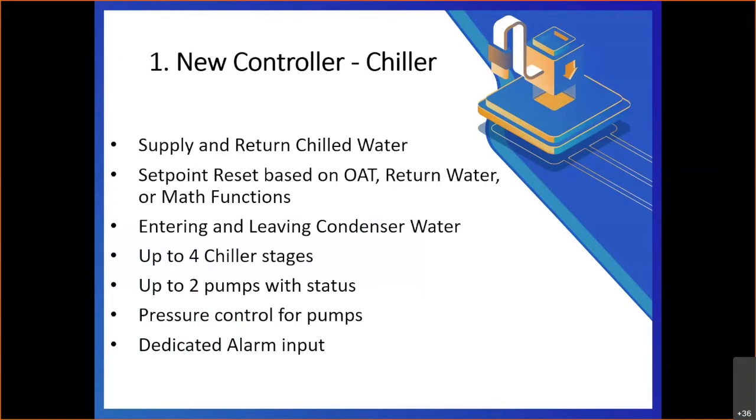And so that is going to be able to talk to, say, a master that it was installed under, a rooftop per se, so that we could get a math function that will represent a cooling demand, and then we can adjust our target set point out of that. This chiller controller is going to be good for both air-cooled and water-cooled chillers. So on the water-cooled side, we do have some safeties that we've integrated in there.